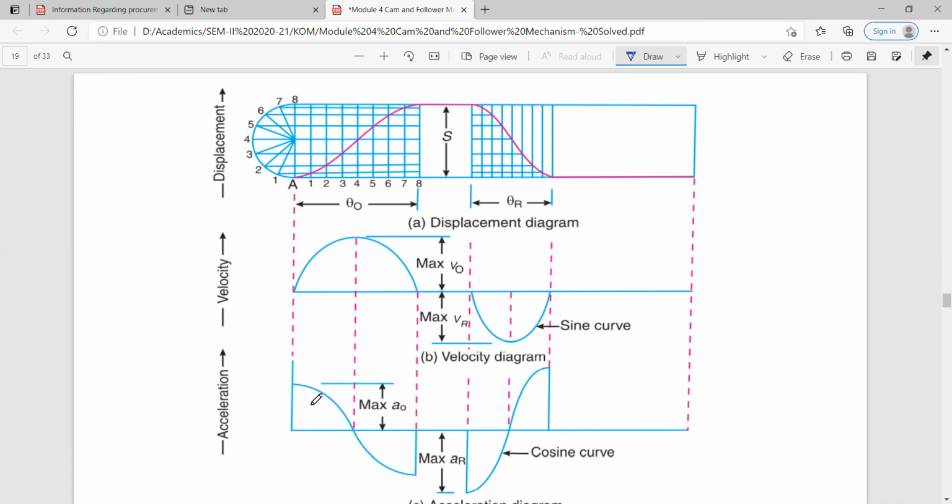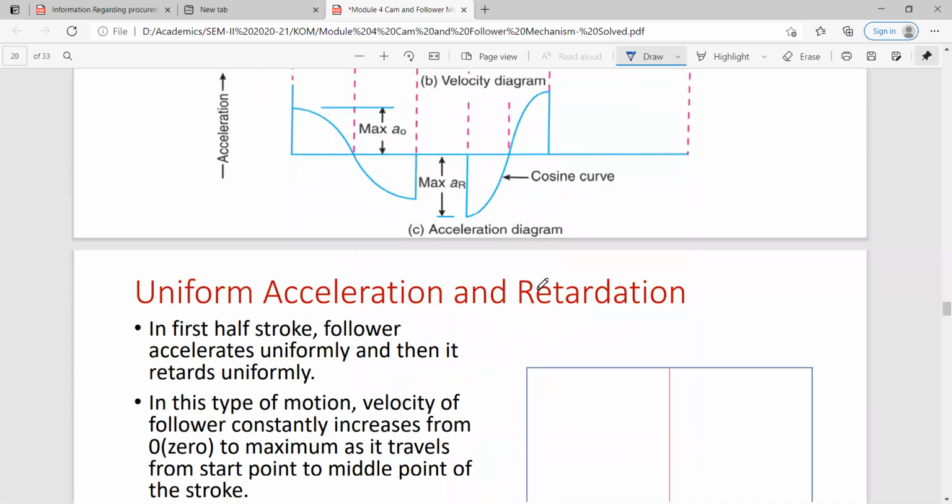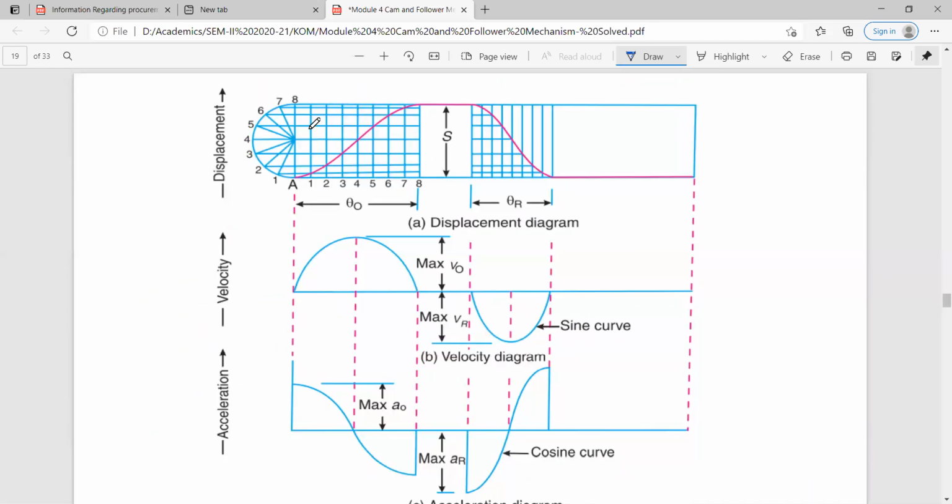Using those values you can vary it, make one short and one long, and draw it like this. Here you can see that below the displacement diagram you also need to draw the velocity diagram. So you will leave some space here, यहाँ पे आपको कुछ स्पेस छोड़ना है इस डिस्प्लेसमेंट डायग्राम के नीचे, so that you can draw the velocity and acceleration diagrams also.